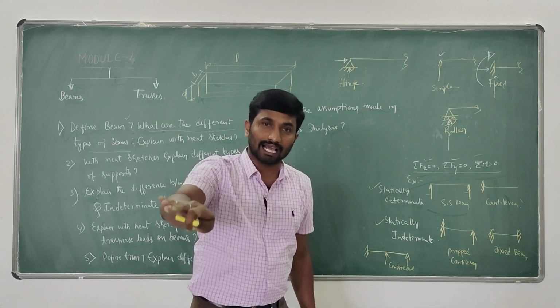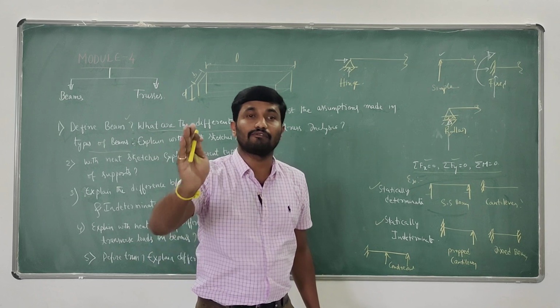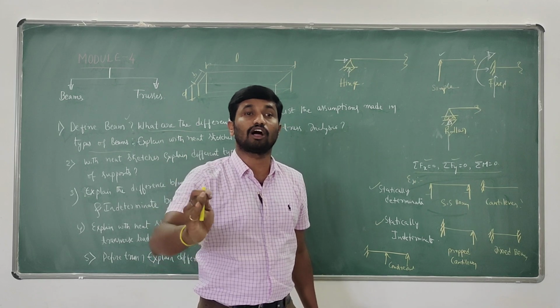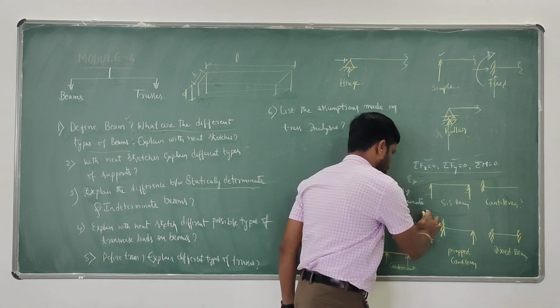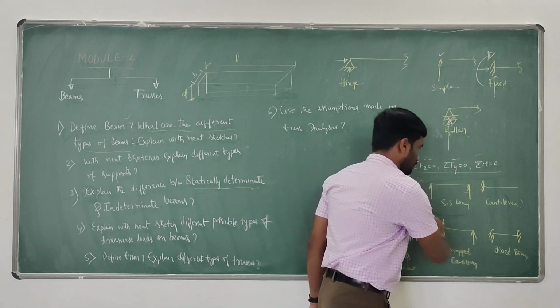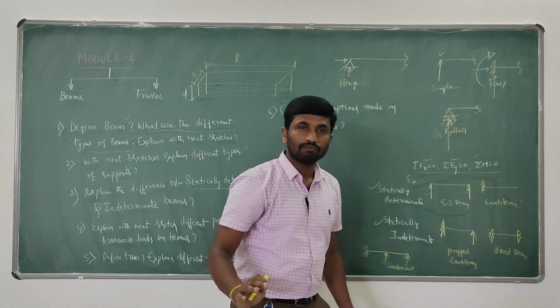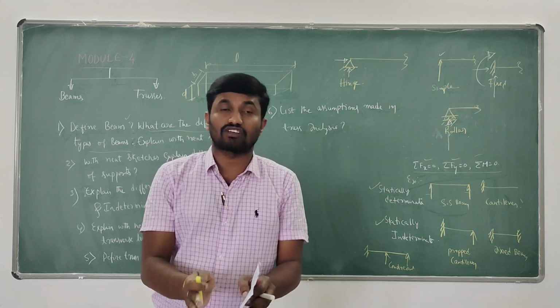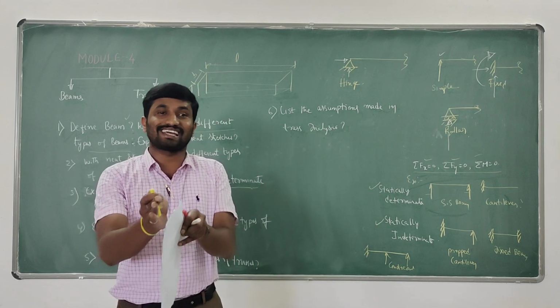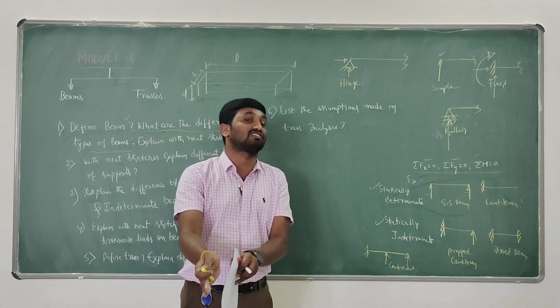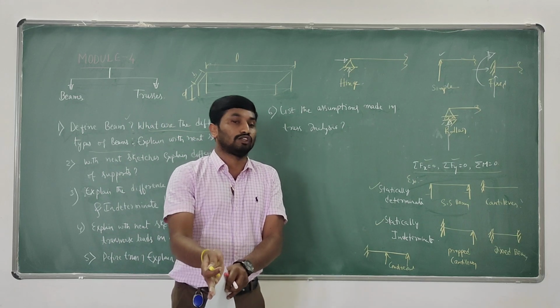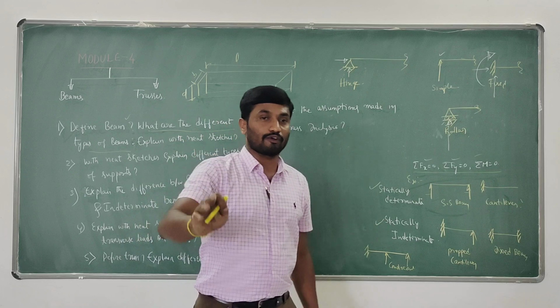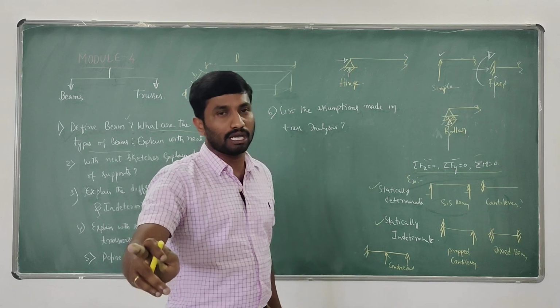The beam which can be analyzed with the help of equations of equilibrium or equations of statics alone is called a statically determinate beam. Example, simply supported beam, cantilever beam. The beams which cannot be analyzed with the help of equations of statics alone, and require extra compatibility conditions or additional equations, are referred to as statically indeterminate beams.